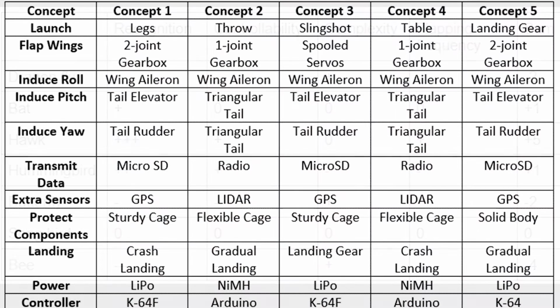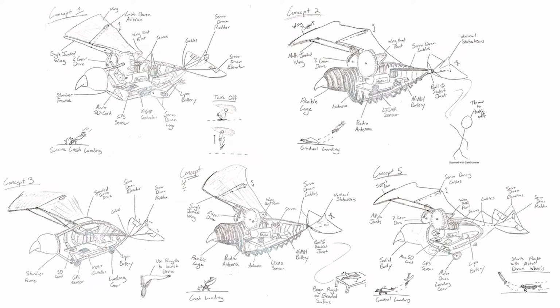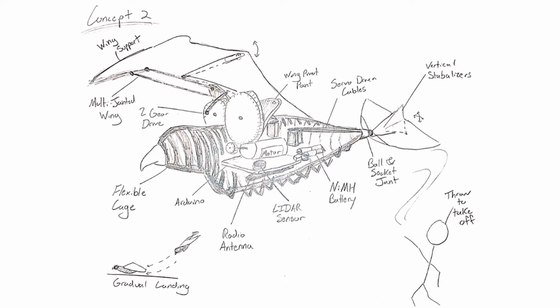After reviewing these requirements and some careful deliberation, we decided to base our ornithopter after a hawk, more specifically, a red-tailed hawk. We began generating concepts using a morphological system analysis. We then drew out each of the concepts and, through the use of an engineering tool called the Pugh chart analysis, decided upon this design, which was our second initial concept.